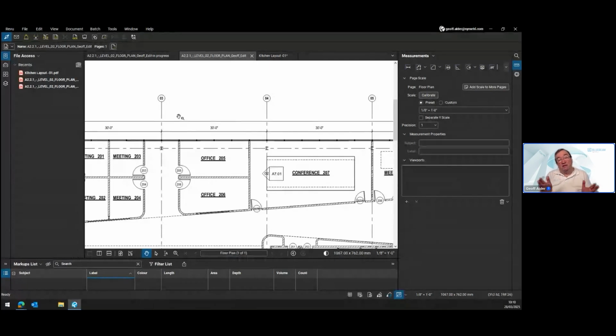Now, if the drawing has grid lines in, I go back to my days, and if I was fitting geometry, fitting doors, fitting skirtings, or fitting walls or whatever, timber in my project, I would always have to refer to a distance from a grid line. So a grid line was always my point of truth all those years ago.